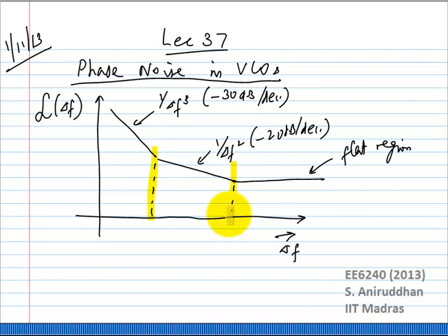So based on LTI analysis, you may get a certain level, but if suddenly you notice that noise is 5 dB higher, you can postulate the presence of some unknown factor S, which compensates or accounts for this extra increase. Now it is not so obvious what this empirical factor is or should be. It definitely does not help predict the noise. It only helps try to explain it in a roundabout manner. Okay, but it still has other strengths, so that is why we will still go ahead and learn it. Of course these are all in log scale as I have drawn it.